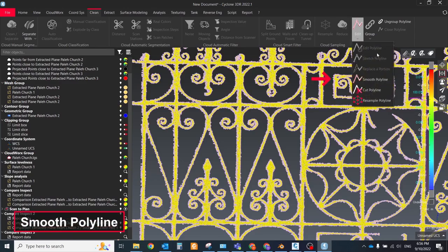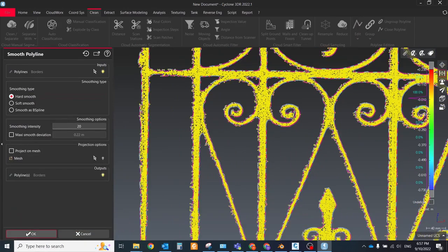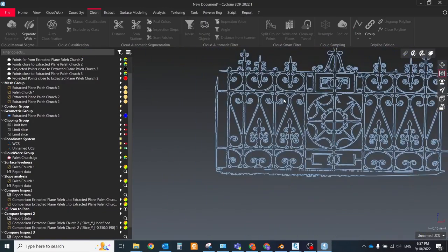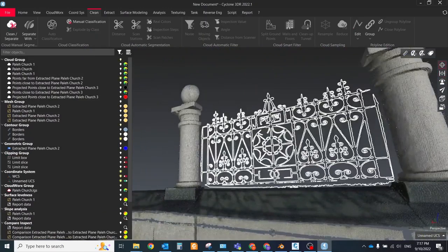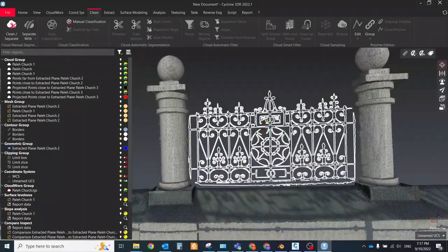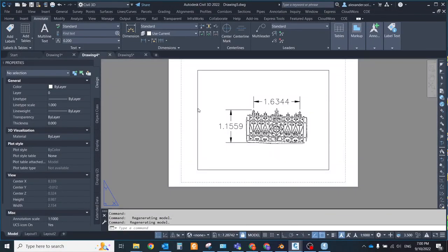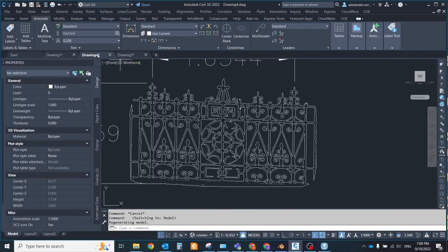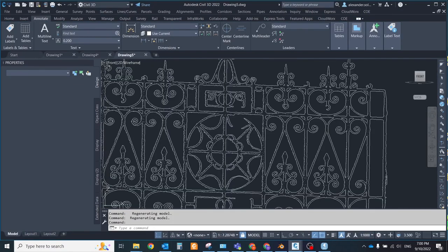It will give you a better shape of the polyline, or extract the polylines as they are with the extract all holes and borders tool and next smooth these polylines. This approach may not give an ideal result, but it is not bad and suitable for a variety of tasks. The polyline can be easily exported to CAD and you can customize the final drawings as you wish.